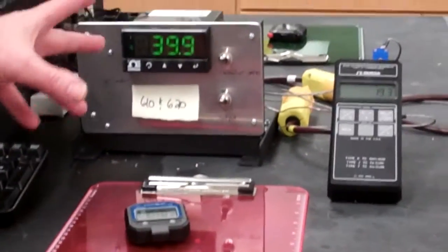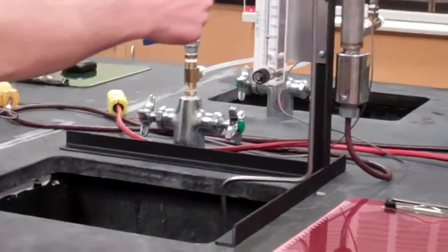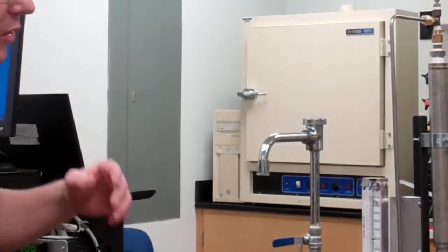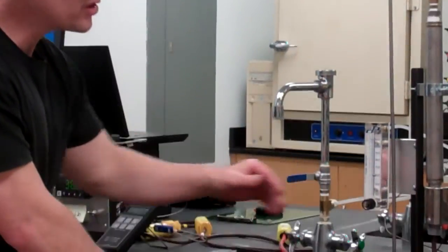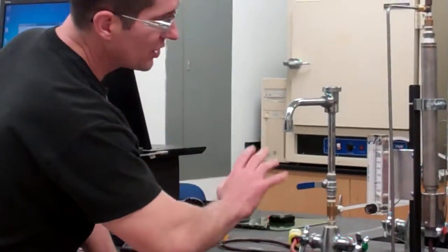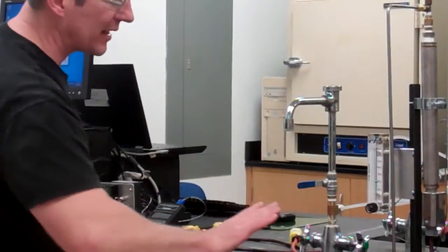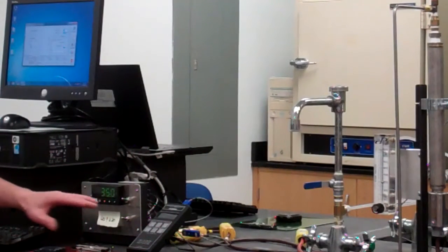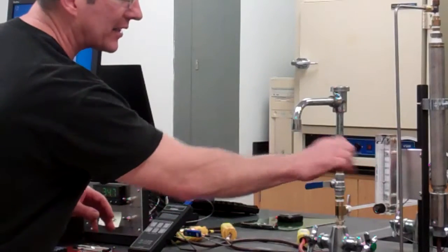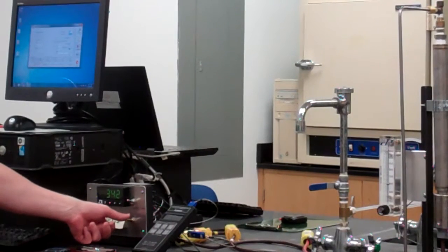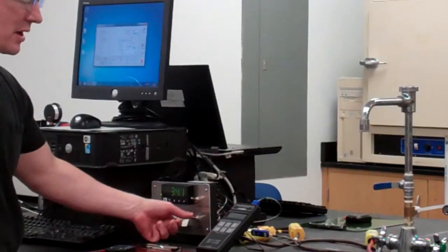In addition, we'll also introduce a disturbance variable, which will be the flow rate through the heater. And so that can be stepped up or stepped down. If you step down the flow rate, you want to be careful not to exceed the 60 degrees C temperature safety point. So, which you can step it up and step it down. Again, just be careful. If you start to exceed that 60-degree temperature limit, there's 2 things you can do. You can either increase the flow rate back to some value where you're going to be below that 60 degrees C, or there's some other issue that you can't, for some reason you're having other difficulties.